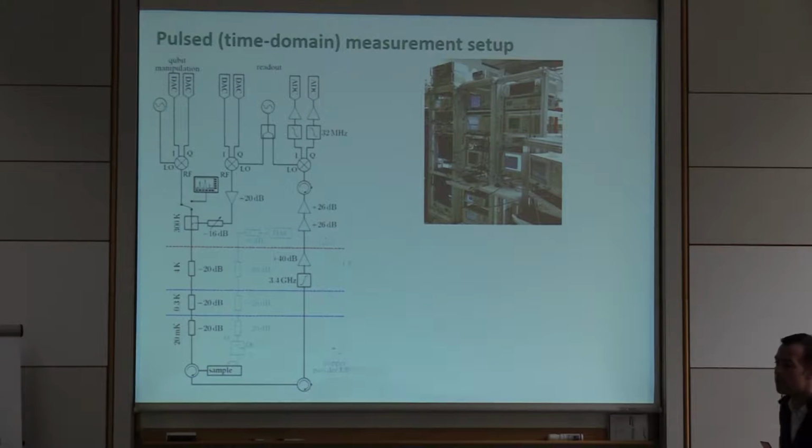Please? What is the second circulator for? Oh, there's a second, yeah. So this is a hot device. It's an active microwave amplifier. How do we couple it? Yeah, we want to decouple, right. So each of them gives us about 20 dB isolation, but we want to have more, like 40 dB or even more. So it's simply decoupling.